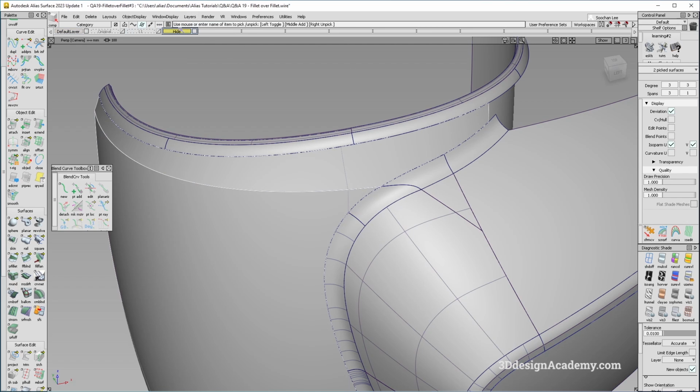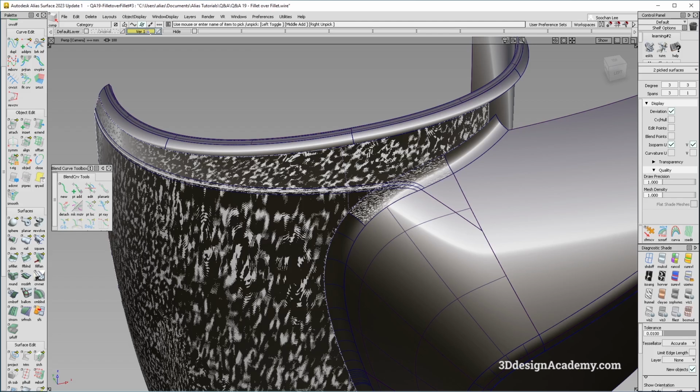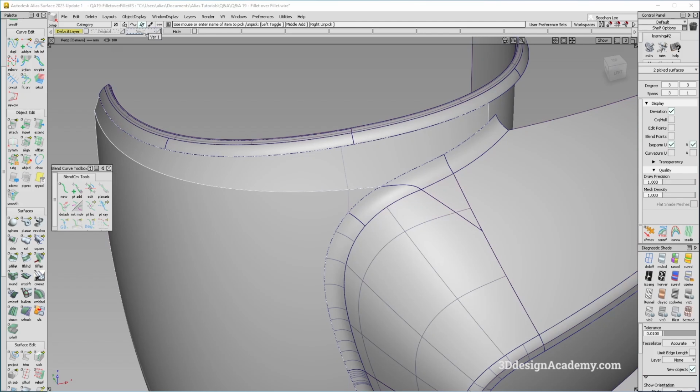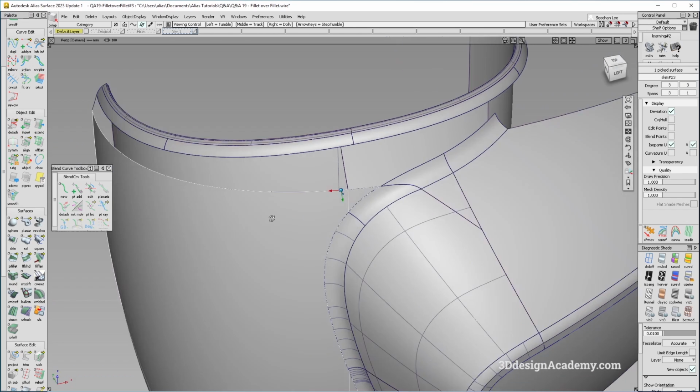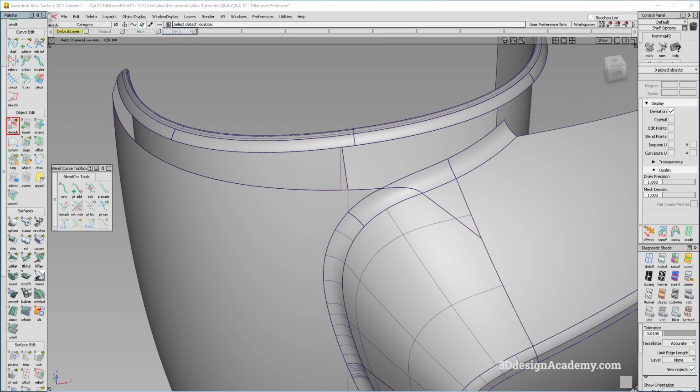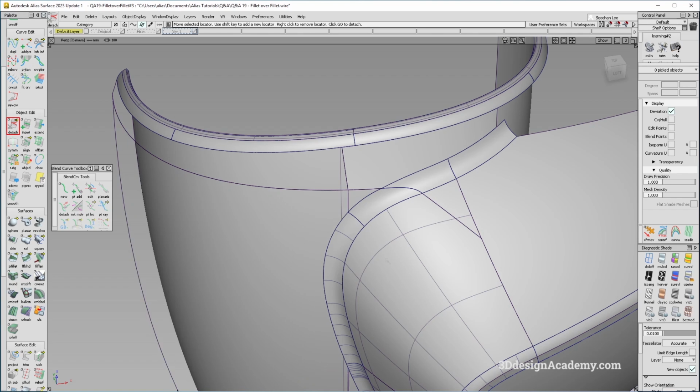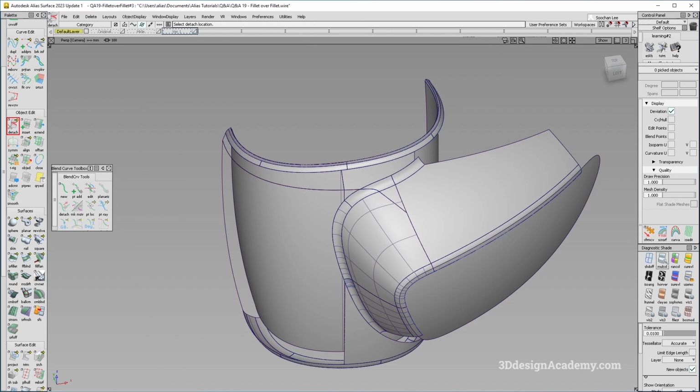I'm going to create a high layer, and this one will be version 1. Let's put it over here like this. Okay, so I'm going to use detach to split this so that it's just a single span surface, because right now it's 3 degrees and 3 spans, which I prefer not to use. So I'm just going to do this. And did it split? Yes, it did.